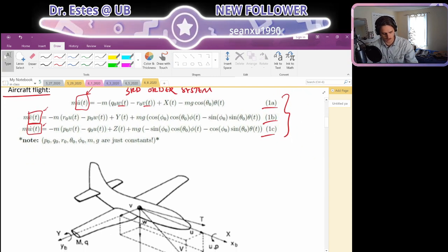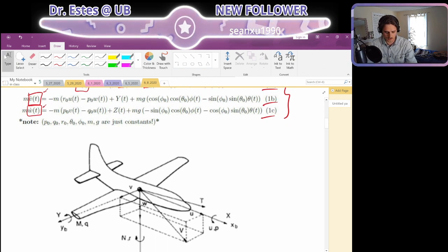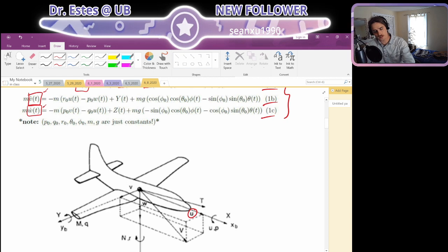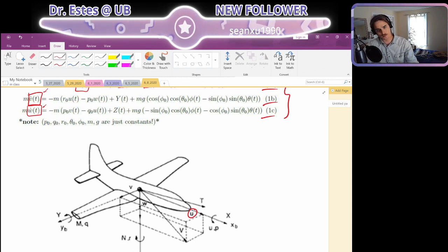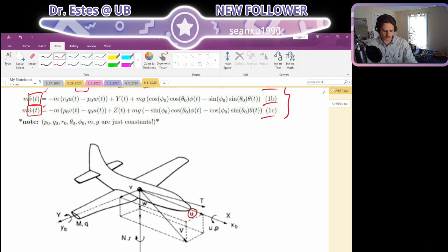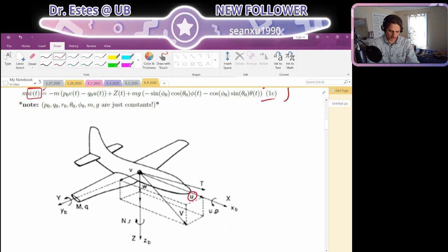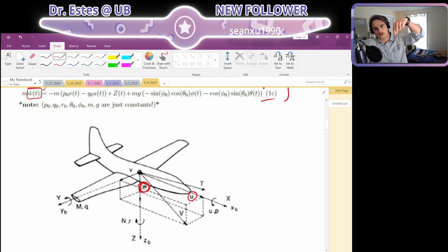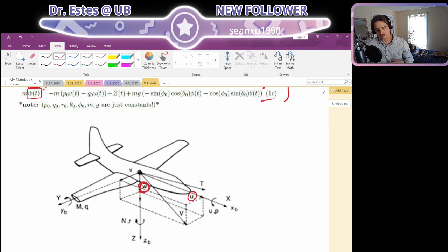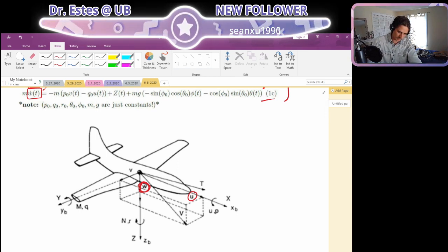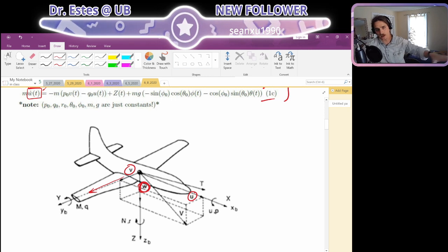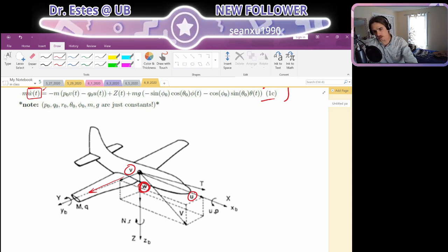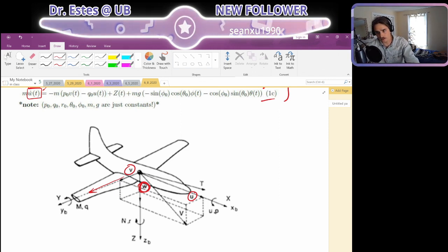And, what is U, V, and W? If you look at this, U represents the longitudinal speed. So if you're looking out the windshield of the aircraft, U is how fast you're going relative to the incoming wind. W is like your speed down. Hopefully that's not going too fast. And V would be the speed outside the right wing. So it's relative to that coordinate system, how fast is the aircraft translating in the sky relative to oncoming wind.